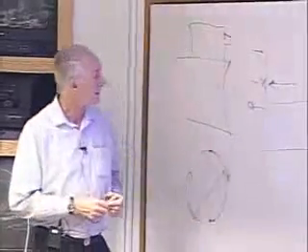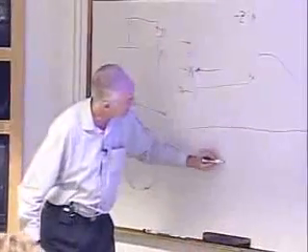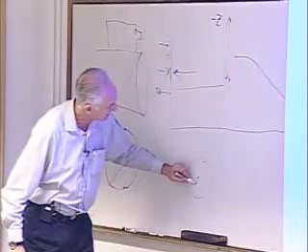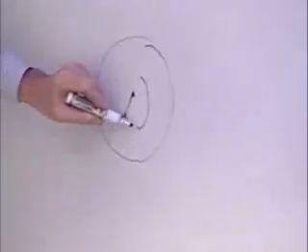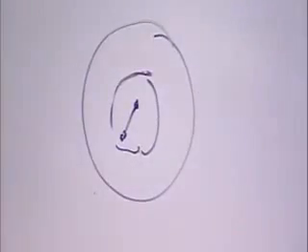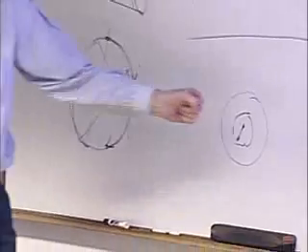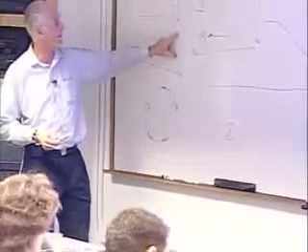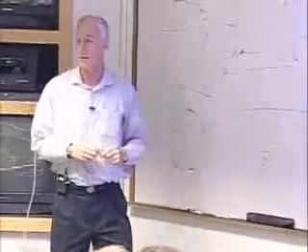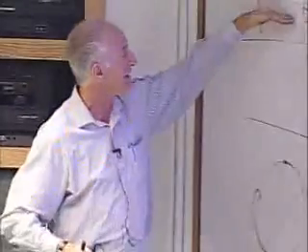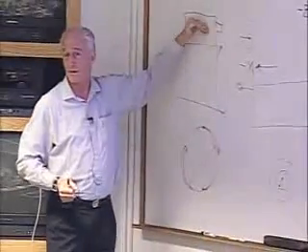So now I'm looking at the television picture, and I see this image. I want to correct it, and move to the side a little bit and go in, but I want to do that in the frame of reference of the end effector. So by going into end effector mode, when I'm working the translational and rotational hand controller, it actually works around that coordinate system.